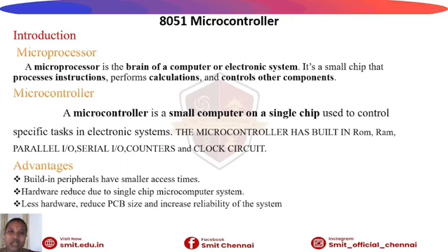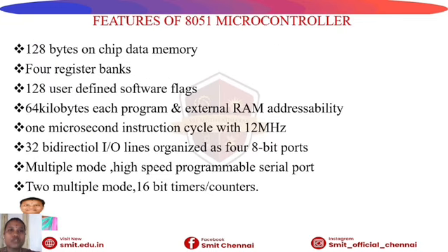And then the microcontroller is built with RAM, ROM, parallel input output, serial input output, counters and clock circuit. The advantages of 8051 microcontroller are built-in peripherals have smaller access times, hardware is reduced due to the single chip microcomputer system, and less hardware reduces PCB size and increases reliability of the system. And the next one is features of 8051 microcontroller.